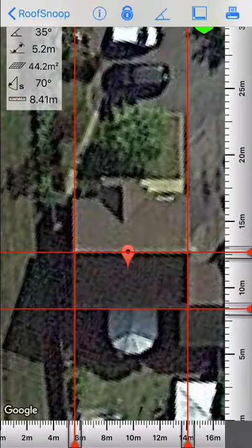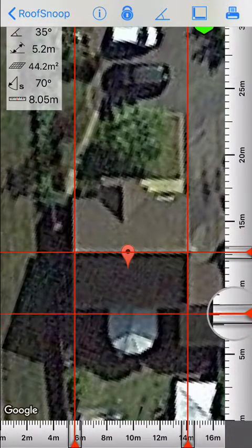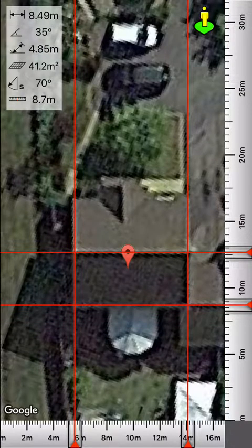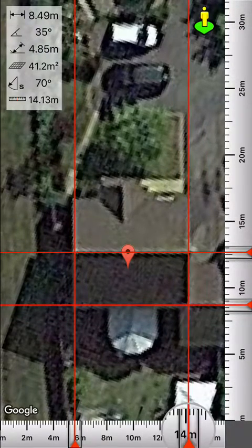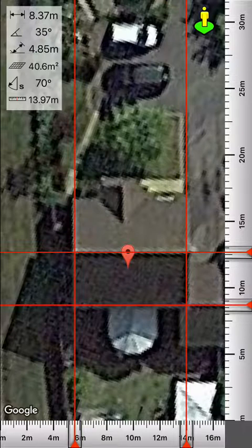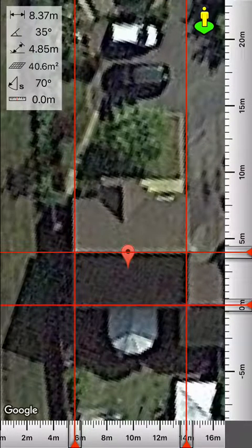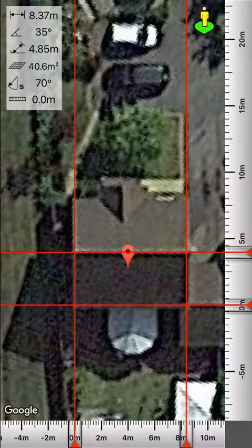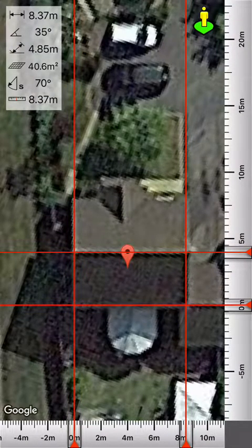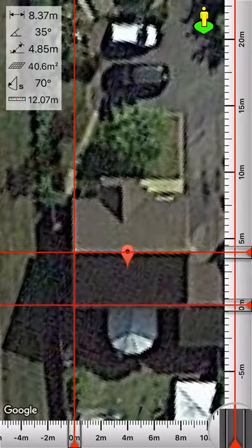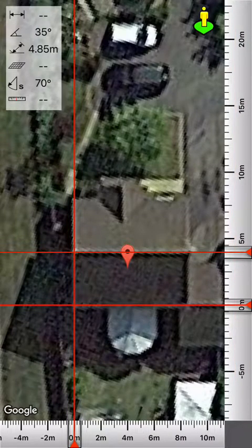The guide can be adjusted by tapping and holding on it over the ruler. The guide can then be adjusted as required. By double tapping on a guide, the ruler will be set to 0 at that point. Here, we zero guides in both the horizontal and vertical axes. You can then see the measurements of the other guides relative to the 0 guide. Also, by tapping on any of the guides, you can read off its measurements in the data panel. To remove a guide, simply tap, hold, and slide the guide over to a ruler, then release.